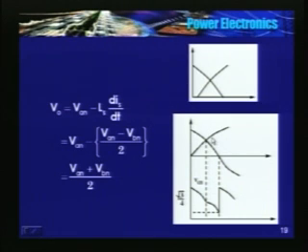So I need to add up these two voltages and divide by 2 to get the output voltage. I am assuming mu to be 30 degrees. At this instant overlap is complete, so the outgoing device turns off completely. Now the output voltage corresponds to the instantaneous value of the incoming phase. So there is a jump.